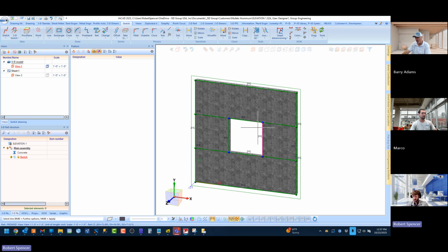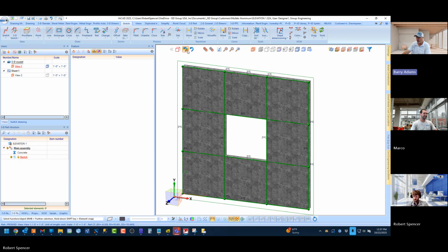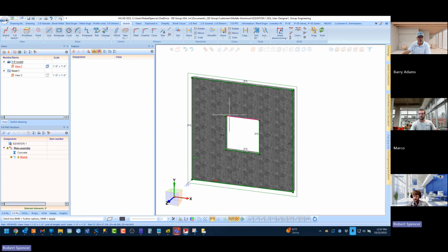And it's the 1 by 1 part that I don't like so much here. Do you have to keep repeating the command, or I got to hit middle mouse button? No, you can just start grabbing. Here, let me back up. So the command stays active. So I drag this one, click, click. Command is still active. Drag the next one, click, click. Command is still active. The command will stay active until you hit middle mouse button or probably escape.